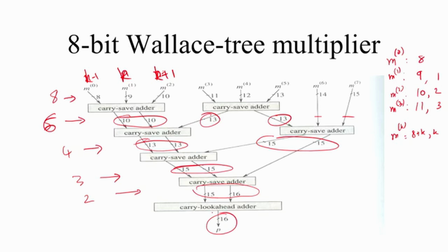But one of the things I need to prove to you is that when I multiply two 8-bit numbers I will get a 16-bit number as an answer, right. If I just say that it is 8, 9 and 10, and if I add three n-bit numbers, then I get n and n plus 1 bits. So if I consider them as 10-bit numbers, and add three 10-bit numbers, this will get 10 and 11 bits, while this will get 13 and 14 bits, and if you start expanding, the answer will not be 16 bits, it will be much larger.